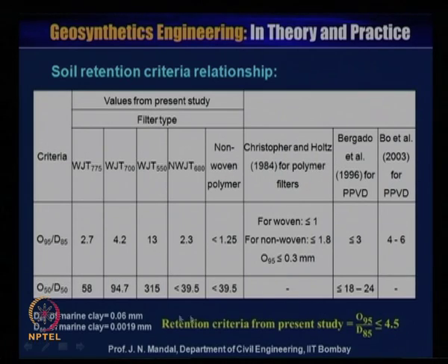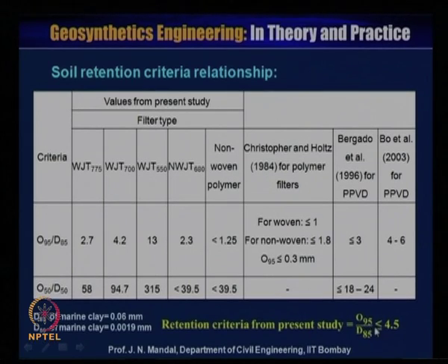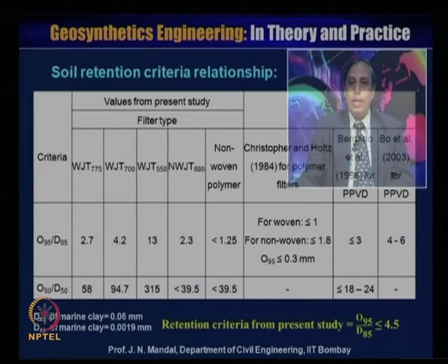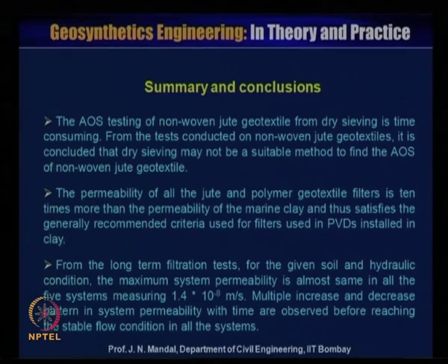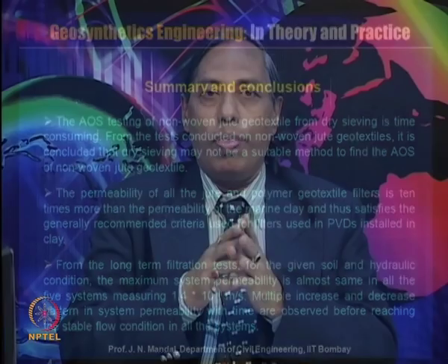So, you can see that in some cases here also this ratio is less than or equal to 4.5. This is the criteria you require. So, it is satisfying the soil retention criteria. Because here soil retention criteria is also very important.